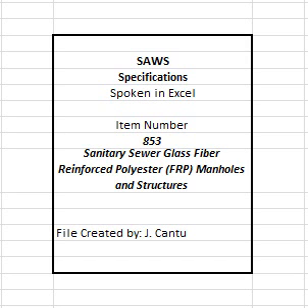5. Set manhole, lift and set manholes and structures per manufacturer's recommendations. A concrete base encasement with steel reinforcements shall be placed at least 12 inches from the manhole in all directions or as per manufacturer's recommendations and extend over the top of the anti-flotation ring a minimum of 12 inches. 6. Backfill material. An approved flowable fill material shall be used for backfilling operations. CDD-853 Drawing Series. 7. Testing.